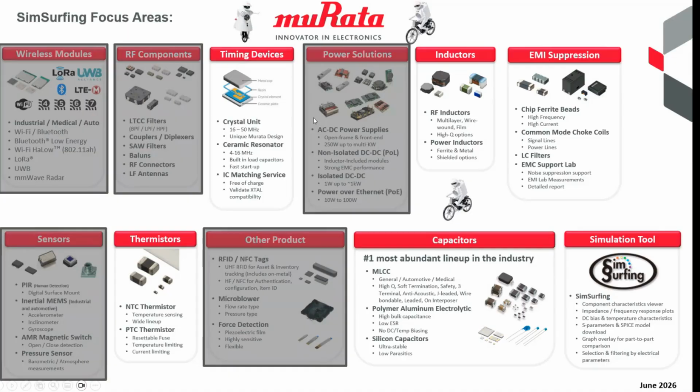So from that broader portfolio, narrowing it down on where SimSurfing will help, I display it here. While SimSurfing supports multiple product categories, it's especially useful for passive components, where you can understand how parts behave individually and in certain applications. That includes caps, thermistors, timing devices, EMI suppression products, mainly ferrite beads, common mode choke coils, and then inductor products, RF inductors, and power inductors.